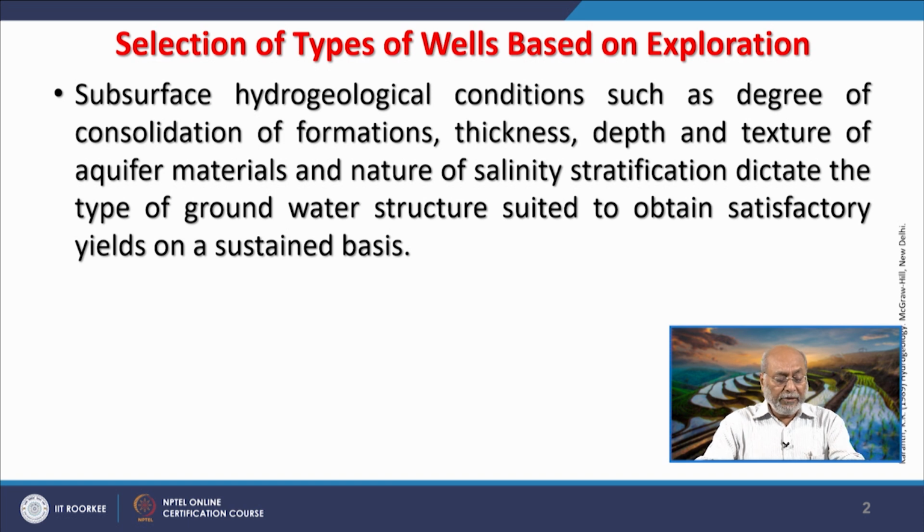As we know, the subsurface hydrogeological conditions, such as the degree of consolidation of formations, thickness, depth, texture of materials and nature of salinity stratification, will dictate the type of groundwater structure suited to obtain satisfactory yield on a sustainable basis.